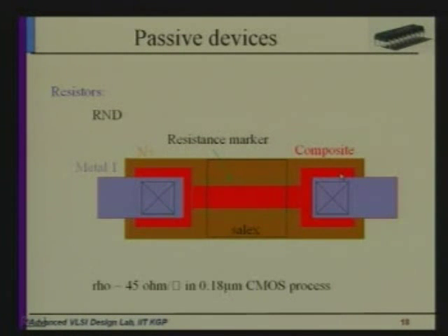Now, if you consider, we have to build MOSFETs, and we also have to build resistances and capacitances on the IC. These are some passive devices, as shown here. First consider the resistance. There are different types of resistance: diffusion resistance, then poly resistance. Are you aware of that? Diffusion, poly, those things. The poly layer, that poly gate, that layer we can also use as a resistance.